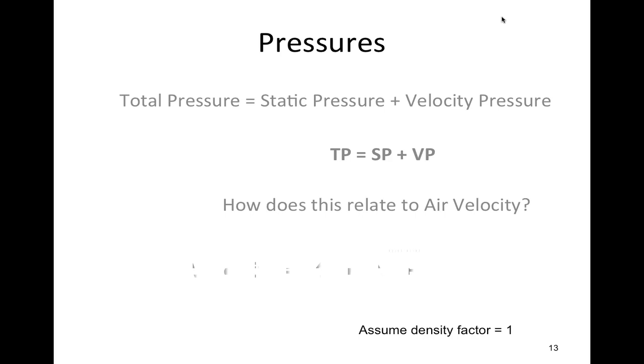The next problem we have is that there's friction on the sides of these ducts. It's not a perfect environment. If you looked at the right side of the movement of air in this diagram, you might call that something called laminar flow. The flow is perfectly even through this ductwork. As far as ducts are concerned, this never happens. The air would have to move so slowly for this to happen that we really never deal with laminar flow.